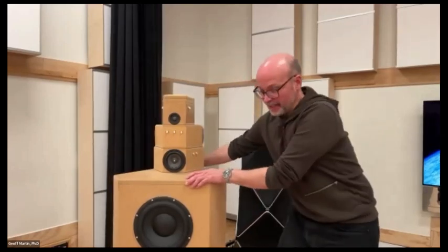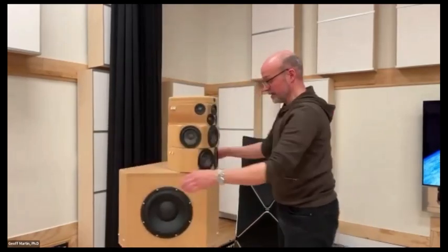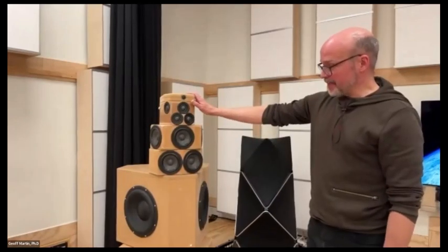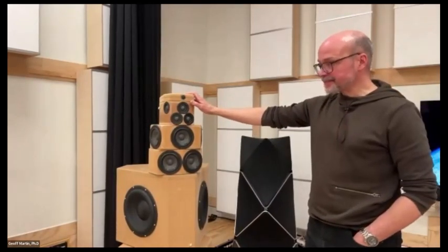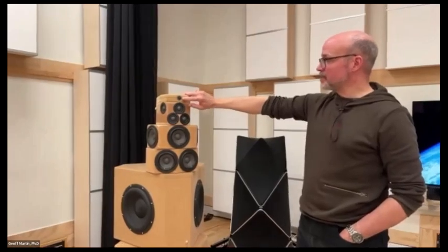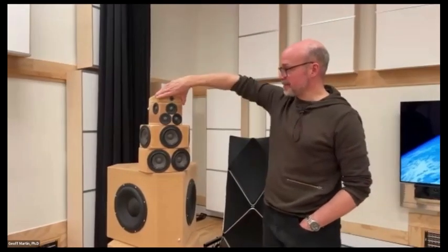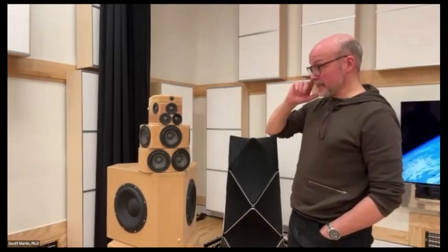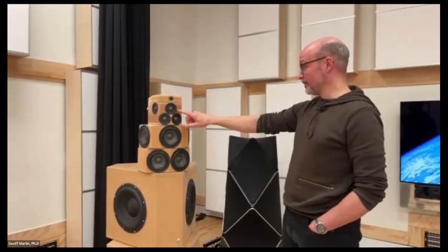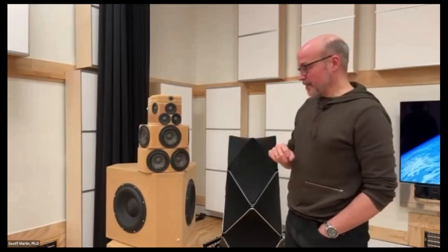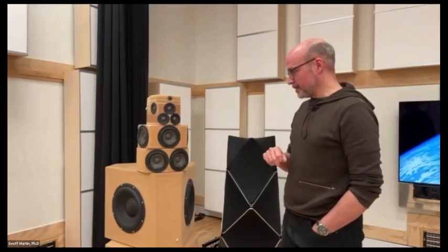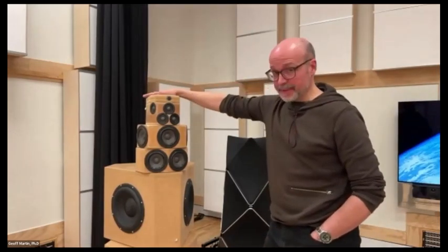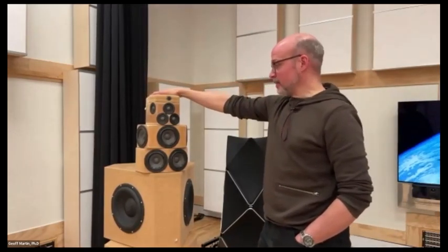And this is what we, in the acoustics department at least, decided would be the final version of the speaker. It turned out in the end that we didn't need this super tweeter or the 8mm dome, so that disappeared because we had such good control of the high end through these 1-inch tweeters that we wound up using. They behave better than the 1.5 inch up at the 30, 40K. But this is what we wound up with in the acoustics department. And we said, this is what we're heading for.